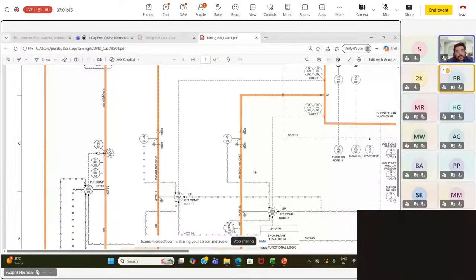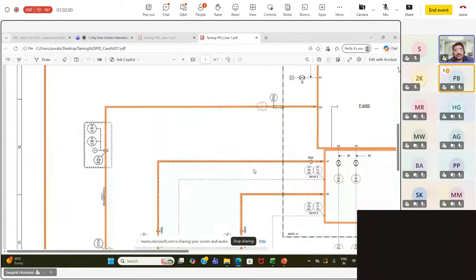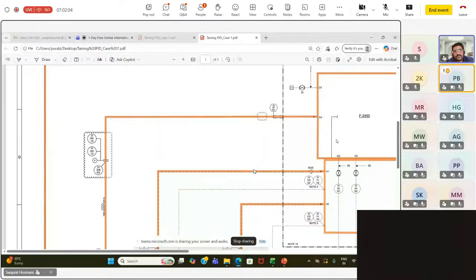So once it sticks open, that may pass full CV or gas equivalent to the full CV of this control valve into your downstream system. So once that happens, in your air startup heater, there is a possibility that this air will blow off the flame, because the flame will not be able to sustain such a high flow rate of hot air. Okay, because it is built for some stoichiometric ratio. So once this happens, this combustion air can actually blow it off.